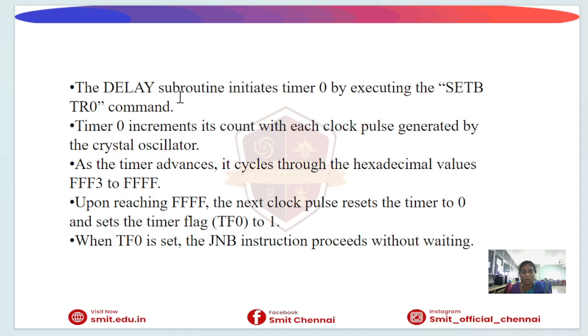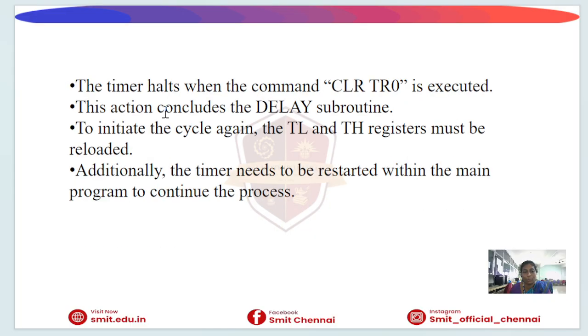So in the delay subroutine operation, SETB TR0 starts timer 0. The timer increments automatically. When the overflow occurs, TF0 becomes 1, and the program waits until the overflow. Then we clear TF0 and clear TR0, which stops the timer, and return to the main program.